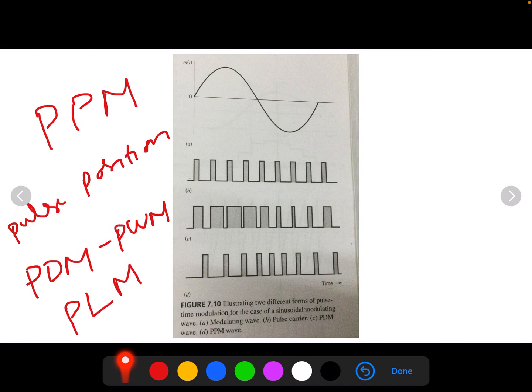In PDM, long pulses expend considerable power during the pulses while bearing no additional information. If this unused power is subtracted from the PDM, so that only time transitions are preserved, we obtain a more efficient type of pulse modulation, that is PPM, pulse position modulation.